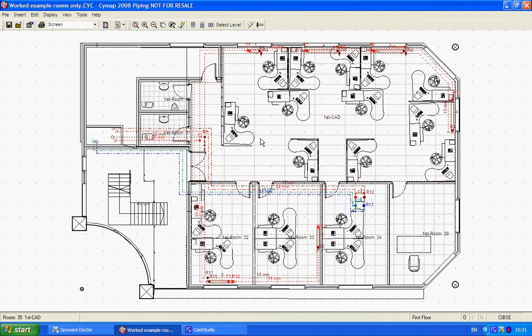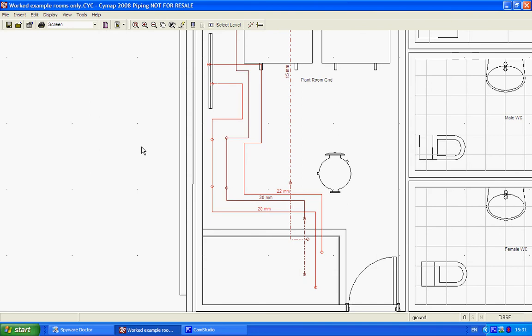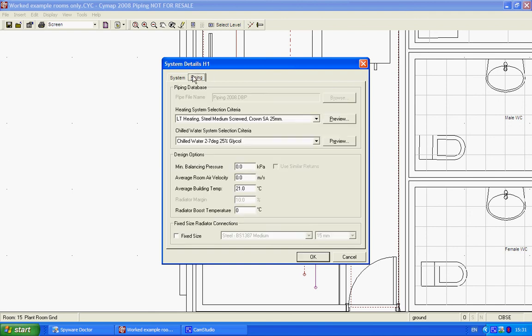The other items the engineer may need to edit are the piping selection rules themselves, the whole basis of the pipe size calculation. This can actually be done by selecting the entry point of the system concerned. For example, if I double click on the entry point with my radiator LPHW circuit, by selecting my piping I can adjust the selection rule.